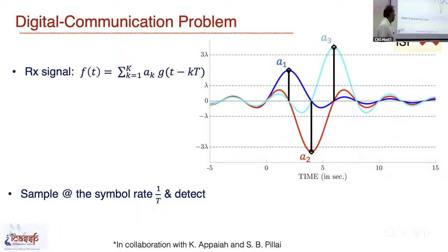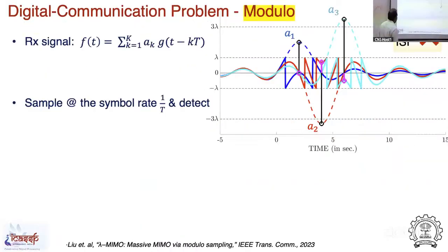Now look at the dynamic range of this thing. This is huge. All this processing that I'm talking about has to go through an analog to digital converter, and then we do all the sampling and everything. What if the dynamic range of the ADC is very small, the way we thought about? We will have some sort of folding here. So look at these signals. Sorry for the messy picture, but we have folded signals right now. Instead of having the original samples, we have these folded samples. Is it fine? Does anyone have any question? I can explain.